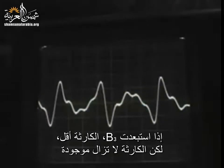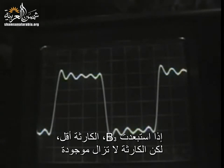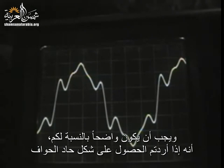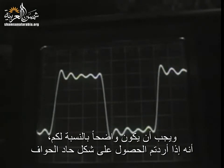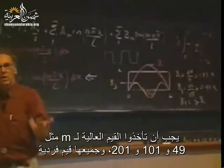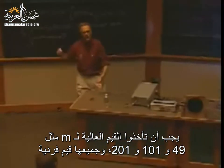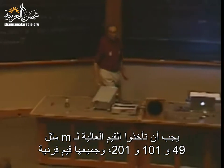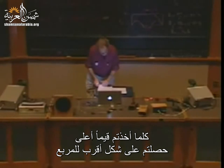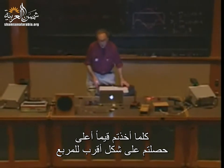If I take B3 out, that is less disastrous, but it is still pretty disastrous. But you already begin to see something that looks like a square slowly. And it should be clear to you now that in order to get the real sharp edges here, you need very high harmonics. You have to go to M values of 49, 101, 201. They're all odd. You have to go to very high values, and the higher you go, the closer you will get to the square.